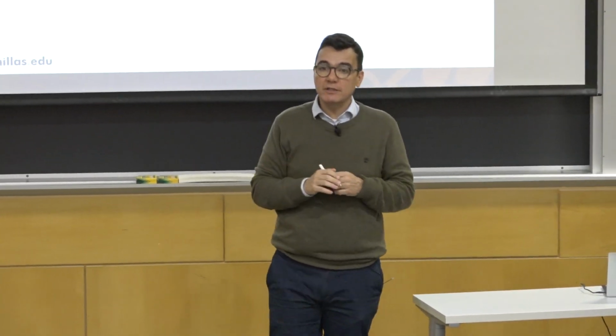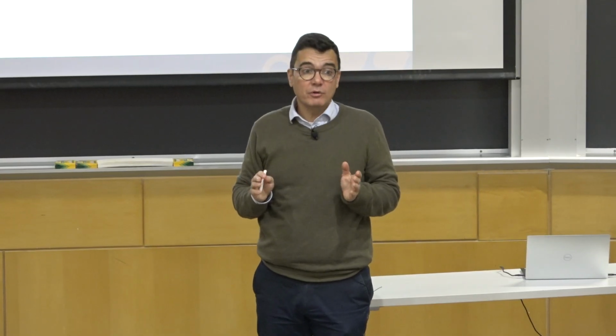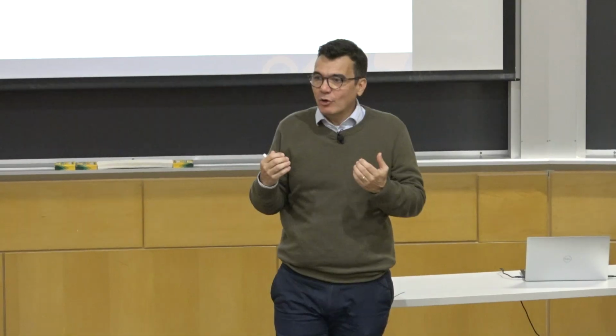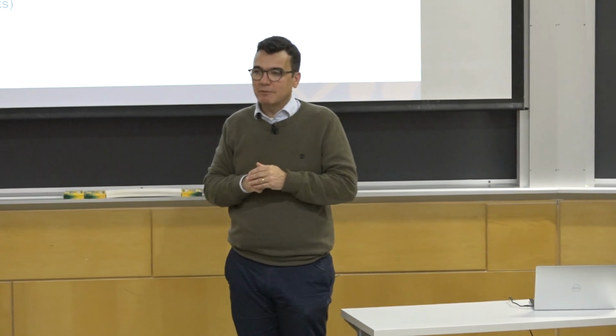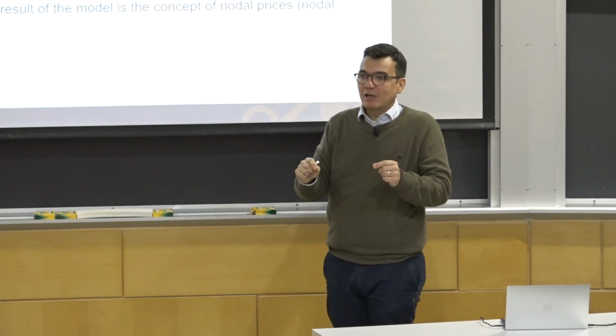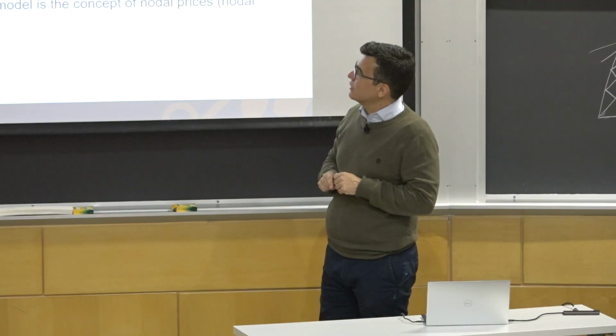What do we have in a direct current system, in a DC system? We only have active power because the concept of reactive power doesn't apply. Reactive power only applies when you have sinusoidal waves and a possible lag between currents and voltages. In a direct current system, we only have constant current and constant voltage, and therefore we only have resistance.